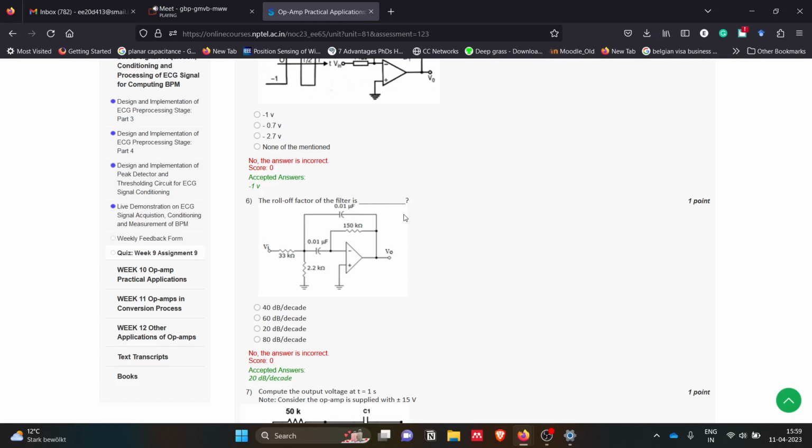Let's say this one is C2, this is C1, this is R3, we have V0, this is R2, R1, Vi. So you will have to get the transfer function by using a simple nodal equation here. Let's say this is the V1 voltage, so (V1 minus Vi) by R1 first, plus V1 by R2 plus V1 S C1 in this branch, because this is 0 volts.